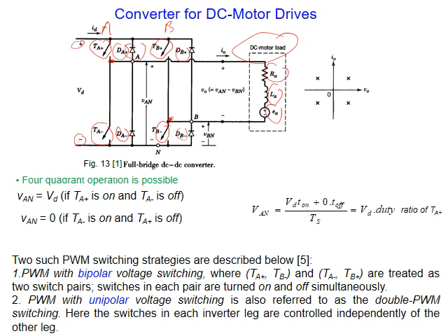You may say, okay, why do we connect these diodes? First of all, to protect the circuit, protect the switch, and to make a path for the current to flow through in the situation where the current reverses direction. As an example, energy stored in the inductance is released, and we can use it.